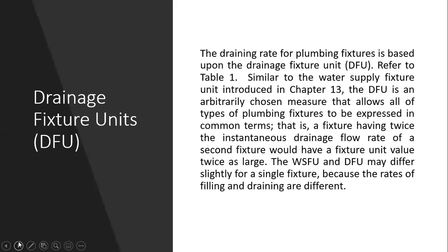Dahil na mag-start ako ang report. Drainage fixture units or DFU. The draining rate of plumbing fixtures is based upon the drainage fixture unit, DFU. Refer to table 1, makita natin ito niya. Similar to the water supply fixture unit introduced in chapter 13. The DFU is an arbitrarily chosen measure that allows all types of plumbing fixtures to be expressed in common terms.